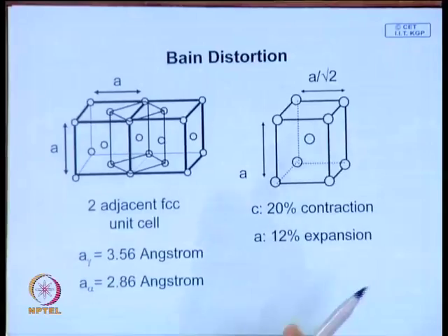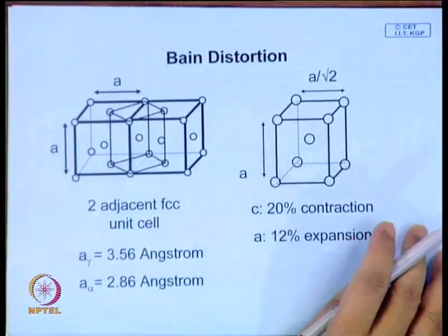Now, last class we talked about how deformation takes place in a martensitic transformation. When you are quenching, at the temperature from which you quench, the structure of steel is austenite, which is face centered cubic structure, and you have some carbon atoms, even if you have 1 atomic percent, mind you.